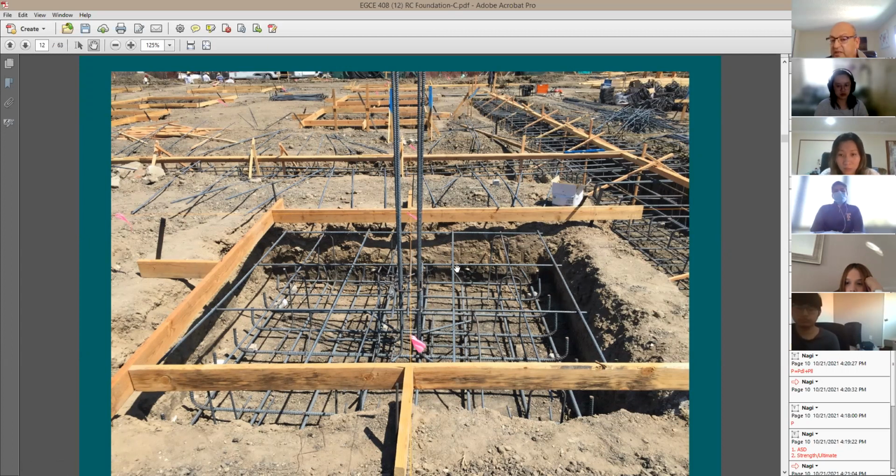Because what happens if you give me the exact hole size, 10 feet by 10 feet? I'm sure some of the soil pieces are going to intrude into the footing, and I'm going to be against this, because I'm going to ask them, where is the concrete cover? I need at least 3 inches. So make this side a little bit larger so that we don't complain. As an engineer going to the site, I'm not going to have any comments.